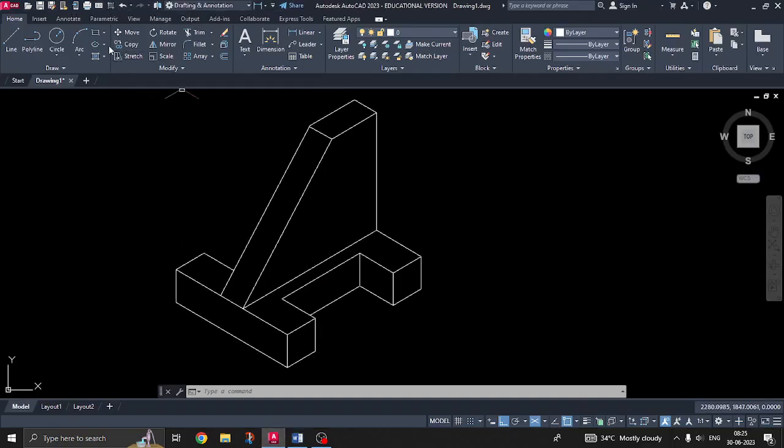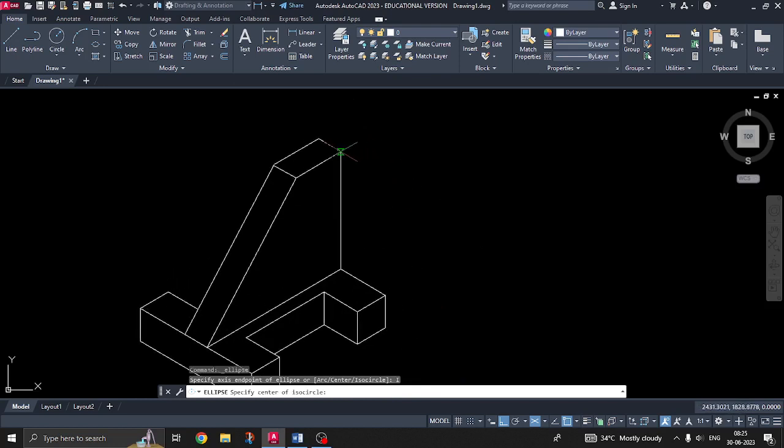this surface. You select the ellipse second option, axis end ellipse option. Center, axis end, two options are there to draw an ellipse. Okay, you select axis end and also you select the iso circle. The options, as you are taking this option, it is showing the option arc, center, iso circle. You click the iso circle. First you draw here at the corner, known corner. Okay, here or here, anywhere you draw. Let us draw here. Click and drag.